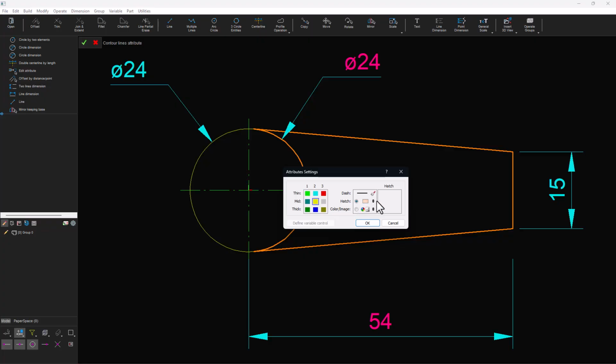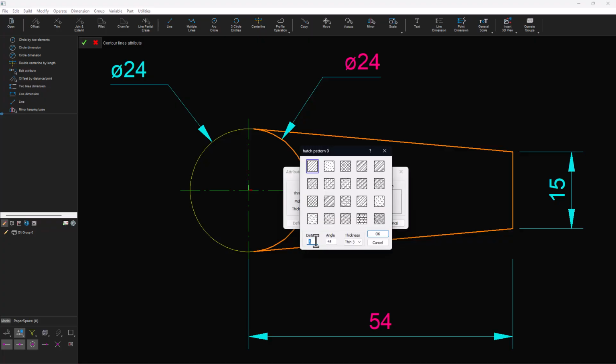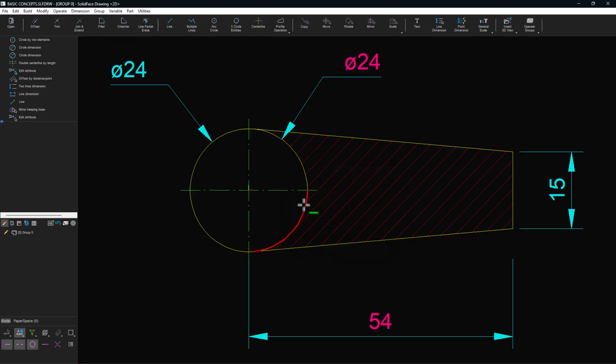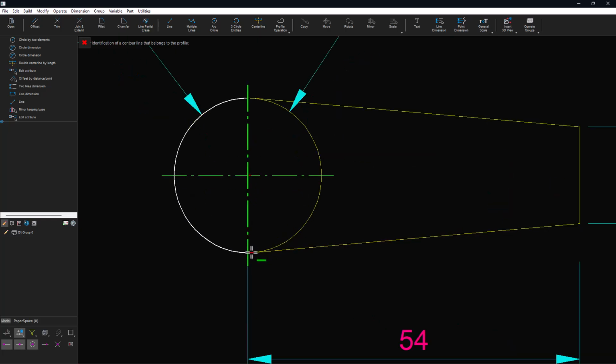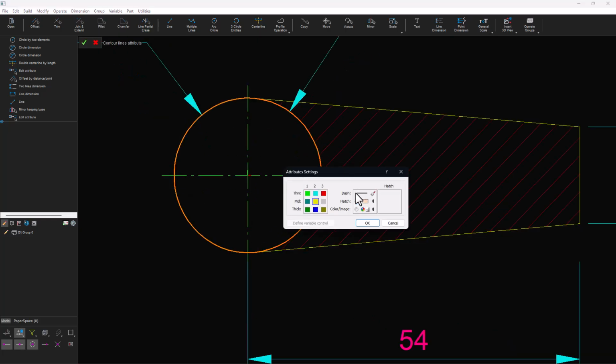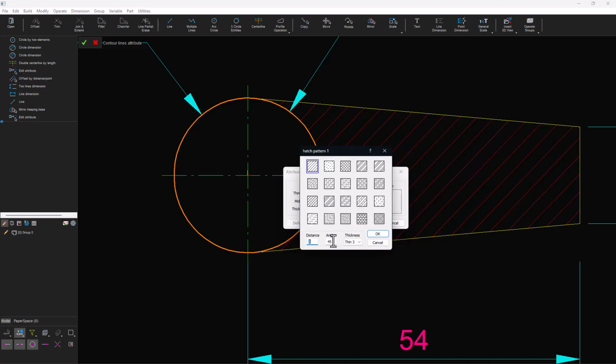Indicate pattern with type and hatching with a distance. See that the contour function created arcs. Select and join them with the Join option. On the left side, create another fill, but using the pattern. Define a new type, angle, and hatch distance.